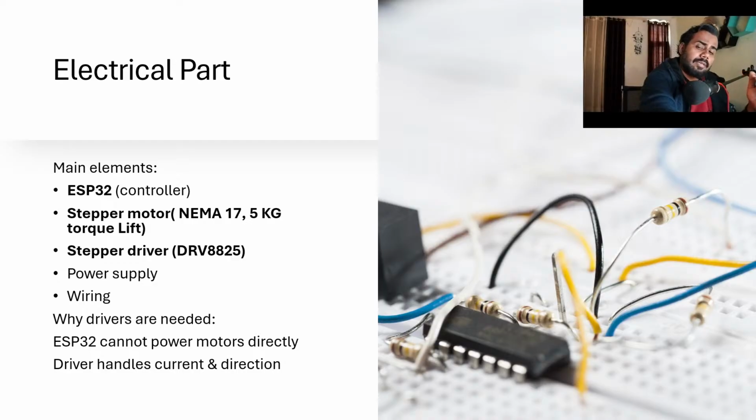Motors fluctuate when they run and stop, so this can burn out our controller board. We don't want that. It's not that expensive, but we don't want to keep buying these electronic parts. So the ESP32 cannot power a motor directly.